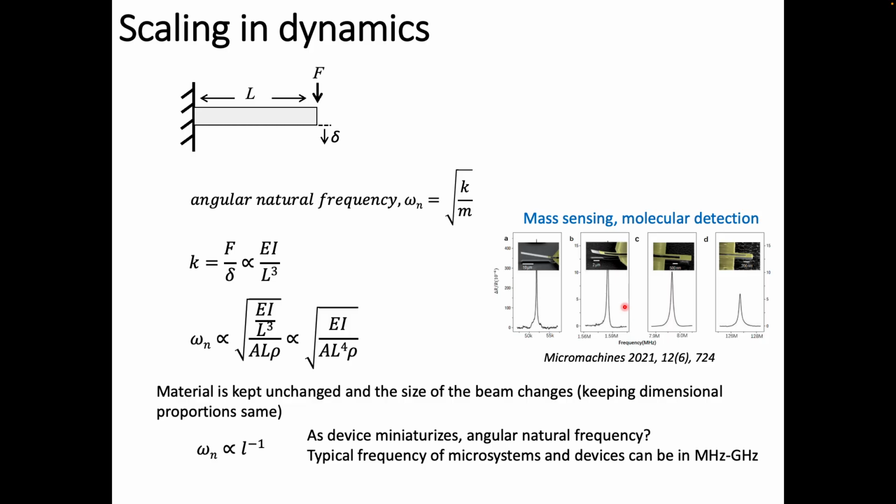Okay, so this is actually quite common technology available here, essentially using this dynamic system. Another example of a natural frequency is the washing machine. Sometimes when you run a washing machine, when you are putting in big blankets, whatever, the washing machine vibrates crazy, right? It bounces around, right? And that is because it was so close to the natural frequency.